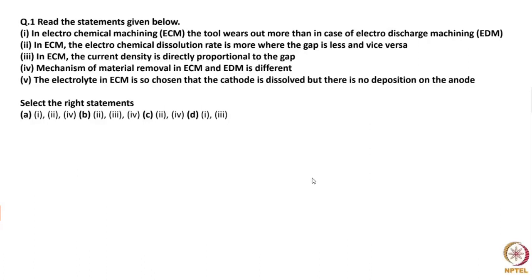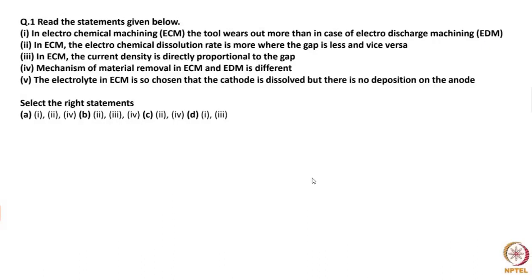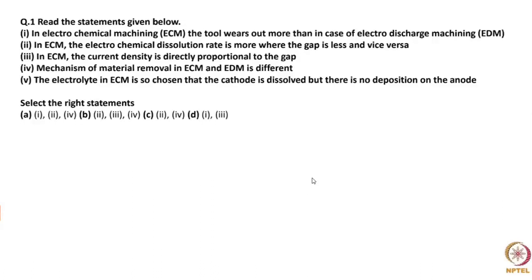So we have seen in abrasive jet machining or in abrasive water jet machining or water jet machining, this energy can be perceived as the mechanical and as the kinetic energy of the jet that hits the workpiece from a chosen standoff distance with given conditions of pressure or traverse rate. So based on that, we have seen the material removal takes place, and we have also come across modeling approaches through which we can predict the material removal rate of the given process.